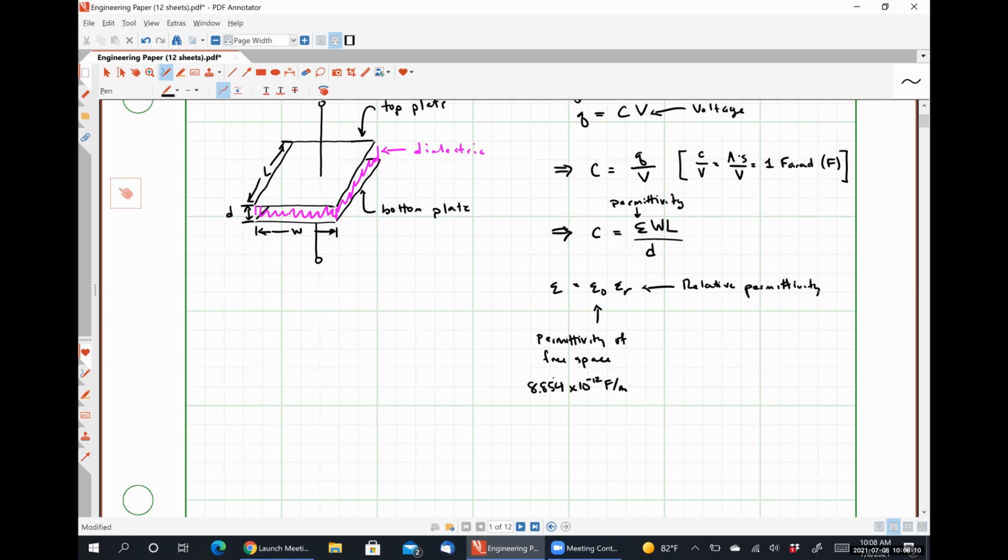And the relative permittivity of deionized water is actually 81, so we could put deionized water specifically between the plates, and you'd get a very, very large capacitor. That is actually something that I did in graduate school, was develop what's called a variable capacitor, which used electrostatic pumping to draw water in between the plates, and you were able to control the capacitance by how much water was in between them.